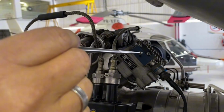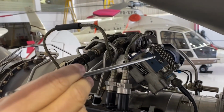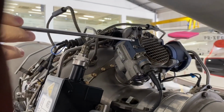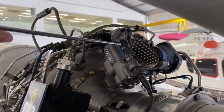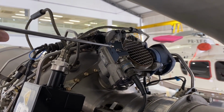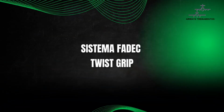The other piece of information for the FADEC comes from this bleed switch. The FADEC needs to know the position of the bleed according to the N1 setting. So here inside the bleed shaft assembly, there is a switch to indicate whether the bleed is open or closed. This is also another piece of information that goes to the FADEC computer.